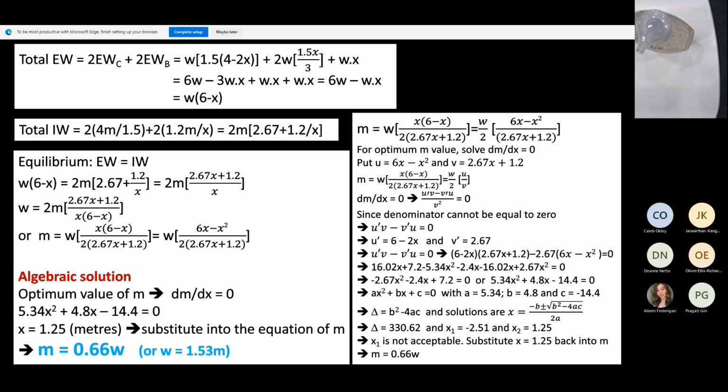So you have x and x, right? So if you have 3 and 3, 6 meters, that's already bigger than the length of the slab. Do you get what I mean? So please don't accept any values that you get here. Always try to think whether the value you're getting is actually sensible or not, as engineers. Okay, so you go back to your problem and see. We all make mistakes, and you get 2.5, for example, which gives you 5, bigger than 4. So reject it. At least if you make a mistake in an exam and you tell me no, that's not acceptable, I'll give you a full mark for it.